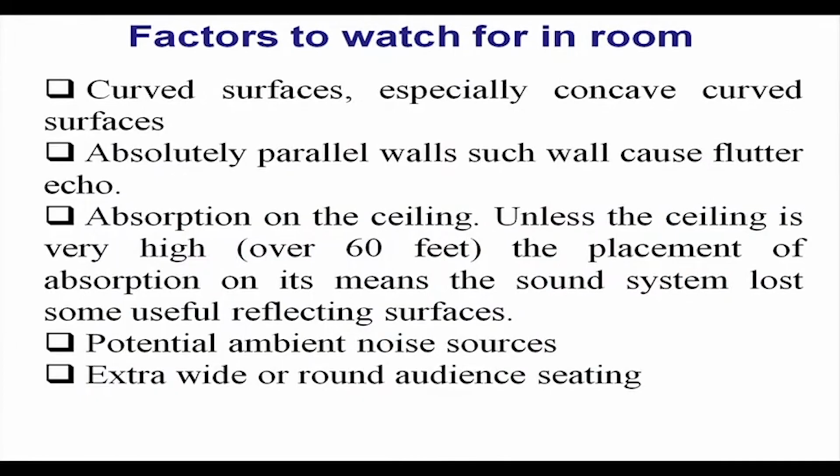Next, factors to watch for in a room. What is the meaning? When you design an acoustic studio, which are the factors you should look at. First is curved surfaces, especially concave curved surfaces. There should not be any concave curved surface. Okay. Then absolutely parallel walls, such walls cause flutter or echo.